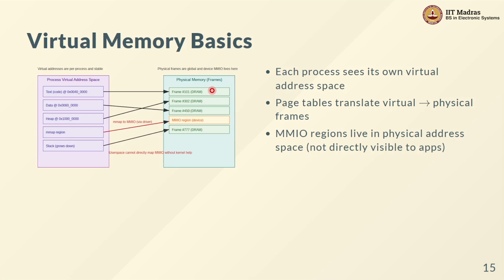In between, I might also find that my DRAM itself has been mapped in a certain way such that there is one range of addresses out here, another range of addresses somewhere out here. And in between that, I have an address which corresponds to the physical address of a device. Now, how do I access a device from a program? I need to use MMIO, right? And that essentially is what I'm calling the memory map region out here.